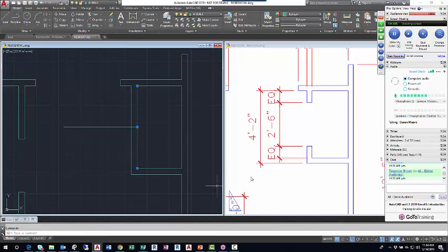So it's kind of weird that the EQ is inside to outside, but that's kind of what they're showing. It's basically centered. It's going to be centered if you were standing with your back to the other closet, looking at the small closet, that door would look centered. That line is in the middle of what wants to be a 2 foot 6 inch opening. If I divide 2 feet 6 inches in two, I get 1 foot 3. So I'm going to offset this line 1 foot 3 up and 1 foot 3 down.